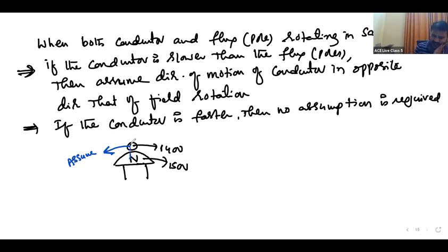And we know the flux direction. Now apply our right hand rule. What is going to happen? Flux direction, motion of the conductor. The current will be inwards. Here it is cross. Therefore, EMF in A is cross in this first diagram.